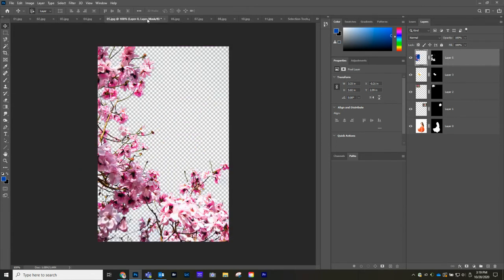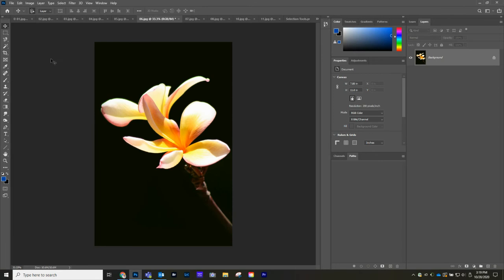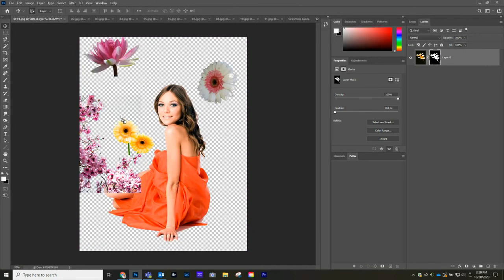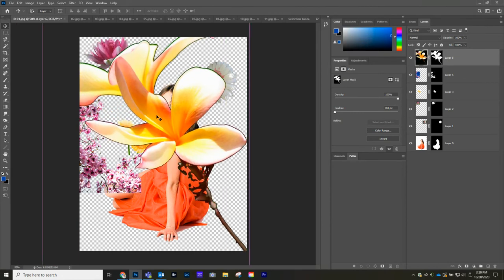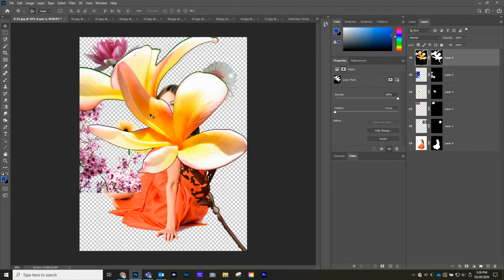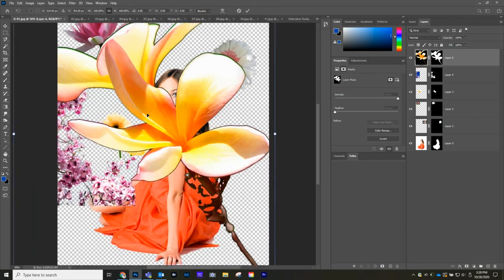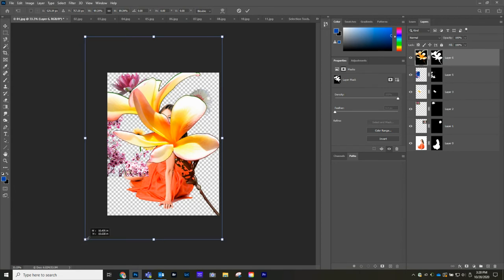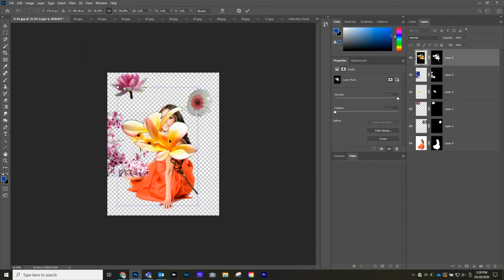All right, so let's move on to number 6 here. This one, now you guys can kind of experiment. Let's see. I'm using the Magic Wand tool. I've selected the black. Let's go select inverse and then mask it. Okay. It's kind of got a fringe around it, but I think it's going to end up being pretty small. Well, actually, when we finally are done with it, it's going to be rather small. This came in very large. So what we're going to do here is go Control T. That's going to allow us to scale it down. Now, sometimes you'll do that and you're like, man, I can't see the transformation box. Control minus, zoom out, and then hold Shift and bring that over here. So actually, this is going to need to be a lot smaller.